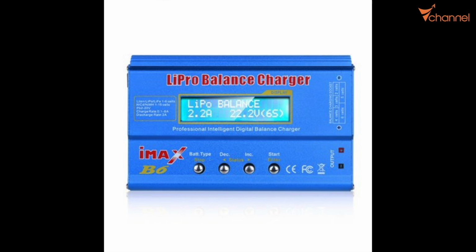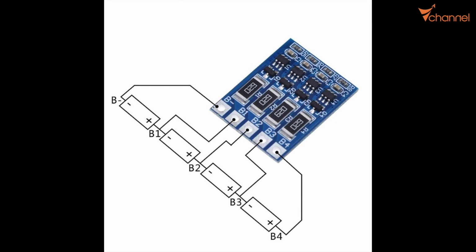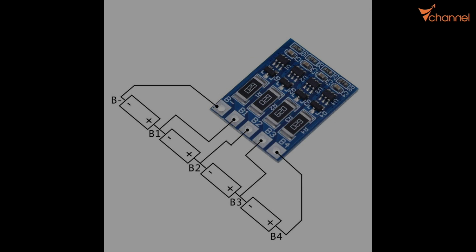It monitors cell voltage so that charging is more even. The battery charger connects like this. In the rest of this clip, I will show you how to connect a balance charger, because balance charging will increase the battery longevity so much.